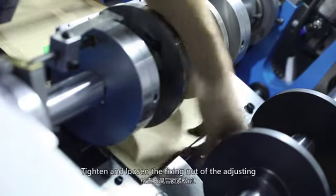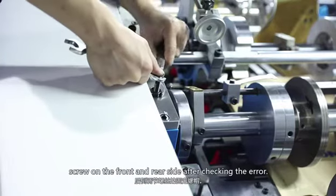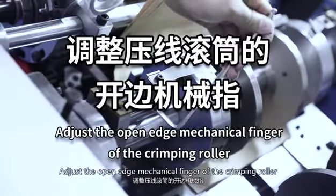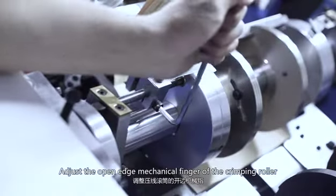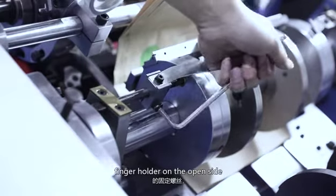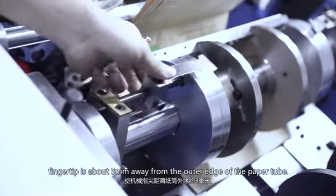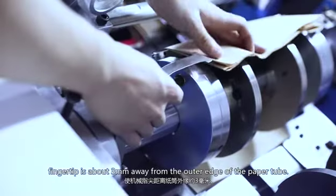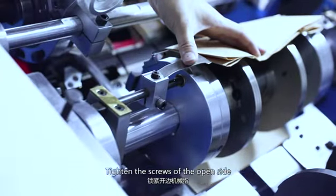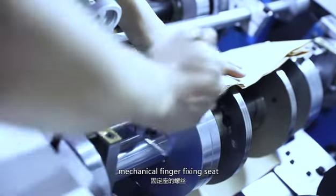Tighten and loosen the fixing nut of the adjusting screw on the front and rear side after checking the error. Adjust the open edge mechanical finger of the crimping roller. Loosen the fixing screws of the mechanical finger holder on the open side and move the mechanical finger holder so that the fingertip is about 3 mm away from the outer edge of the paper tube.